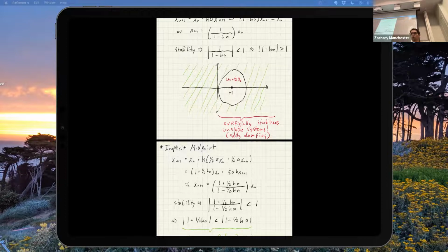And if you're trying to run controllers and stuff, you probably are going to have a fixed time step for your controller, right? So you don't necessarily want variable time step adaptive Runge-Kutta stuff. And on stiff systems, like we talked about, the adaptive step stuff might have to shrink the time steps really tiny to not blow up. And then it takes forever to simulate, right? And it might bog down in certain situations.